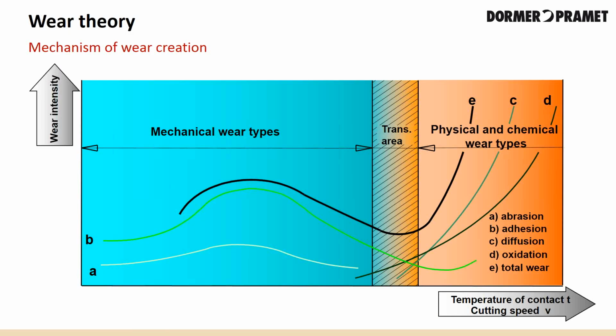Tool wear is characterized by two types of phenomena, namely mechanical and chemical. When a mechanical type wear occurs, the insert is damaged by outgoing chips from the workpiece material. This does not change the chemical composition of the surface layers of the cemented carbide. When a chemical wear occurs, the chemical composition on the surface layer of the tool material comes in contact with a chip. This change usually deteriorates the mechanical properties of the surface layers of the tool material and hence their resistance to abrasive wear.